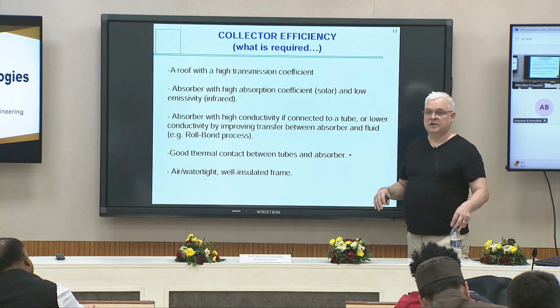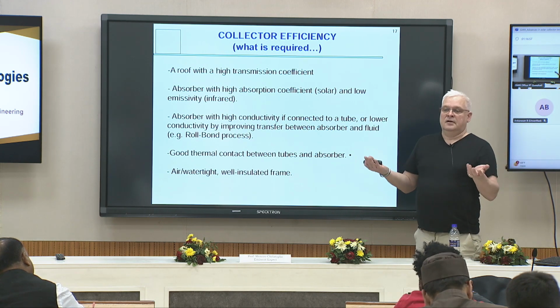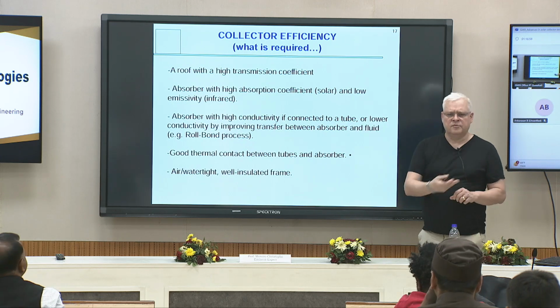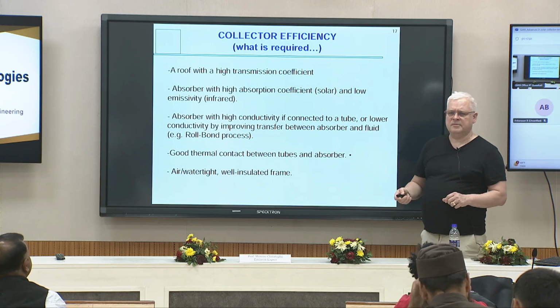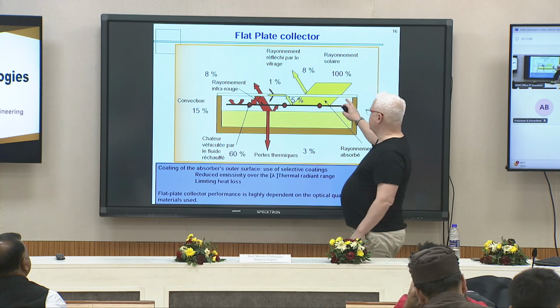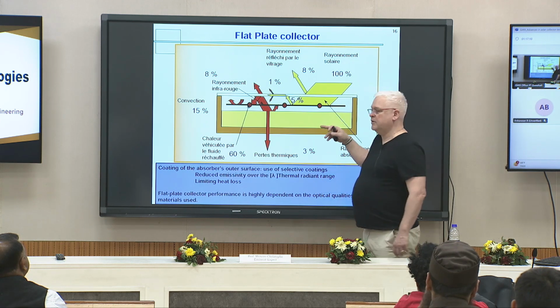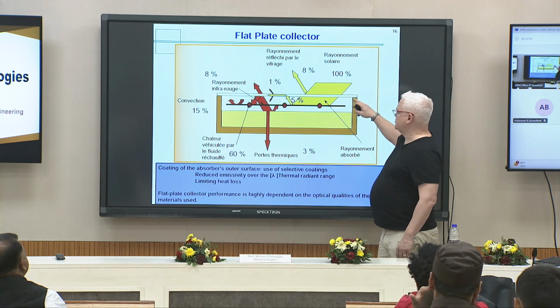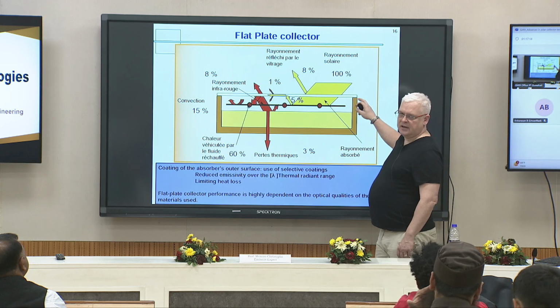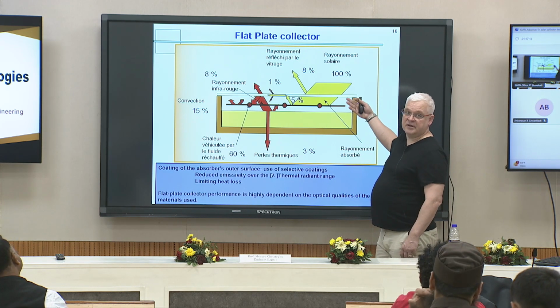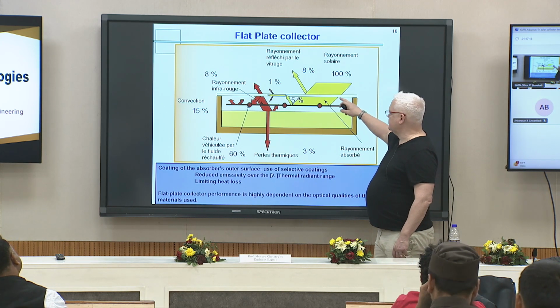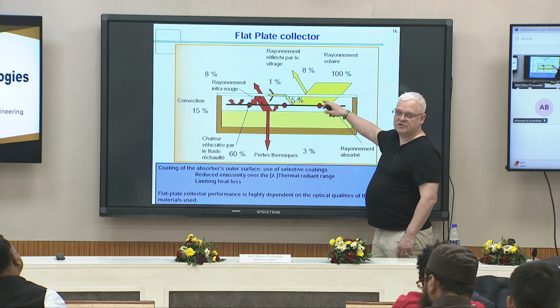If you have an air leak in your collector, that means you will have humidity that can come in. Sometimes you see that when a solar thermal flat plate collector is bad or old, there is very often an air inlet that appears, and then with humidity, sometimes you will see some condensation.